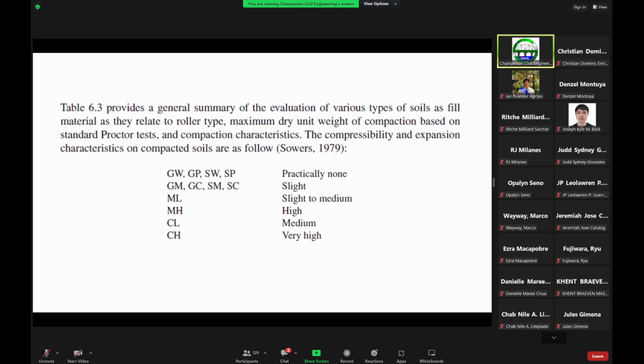Normally, when we prepare geotechnical reports, aside from giving the allowable bearing capacities of the soil, as well as the pile capacities of the soil with respect to either bored piles or driven piles, we also make geotechnical assessments such as the determination of the expansive soils with respect to your soil layer depths in that particular area, as well as soil collapsibility, as well as liquefiable soils. So these are quite problematic with respect to construction.